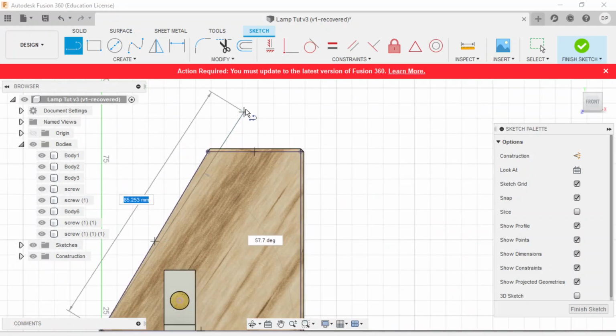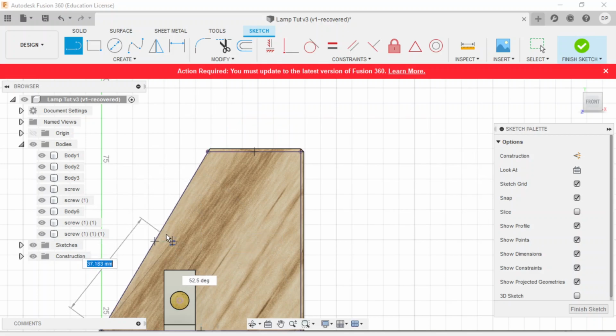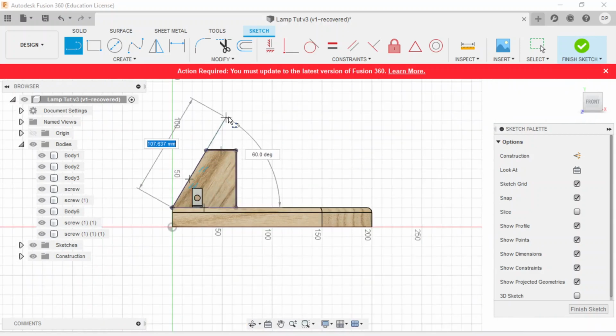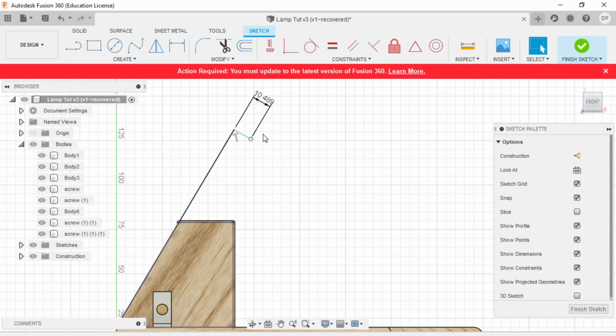So I actually want it to go past this part of the stand, and I want to go through it. As I bring it over here, we see how we get these blue dots forming. So it's determining, hey, be parallel with this line. As you see, look over here. You see how it has those parallel lines? It says make these two lines parallel. And so I can actually extend it to some significant length. Let's say I'll just pick a length for now, and then I'll press enter. Oh, sorry, not enter. I should have pressed escape.